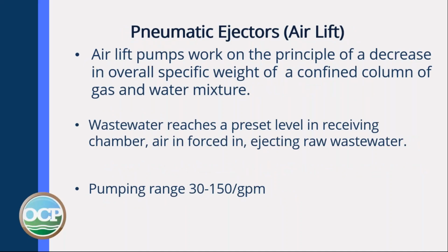Airlift pumps work on the principle of a decrease in overall specific weight of a confined column of gas and water mixture. So as it pumps that air in, the air bubbles coming up push the water out with it. As wastewater reaches the preset level, air is forced in, ejecting the raw wastewater.